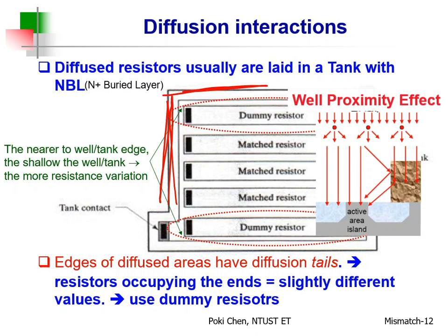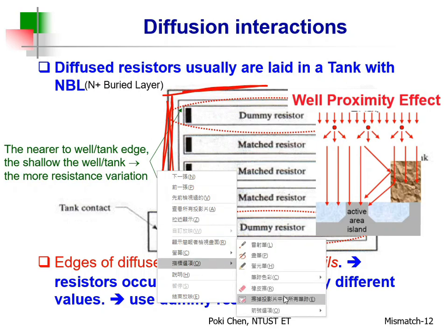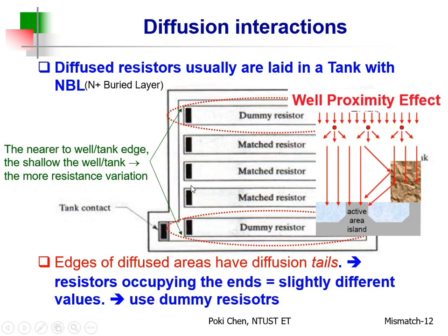Later I will show you some experimental results from TSMC, the best on earth. Even from TSMC, it shows some results to warn the layout engineers. Again, keep your critical devices far away from the well boundary. 如果你的元件很敏感，那你就滚远一点，不要靠太近不要靠边边太近。Maybe you will ask me, how far do I need to go away from the boundary?